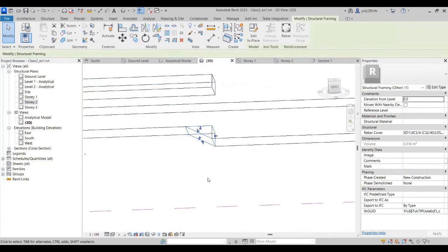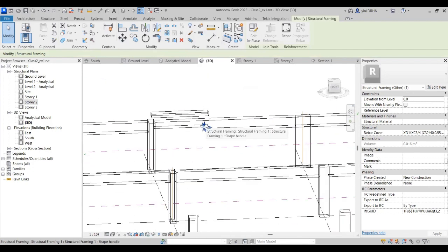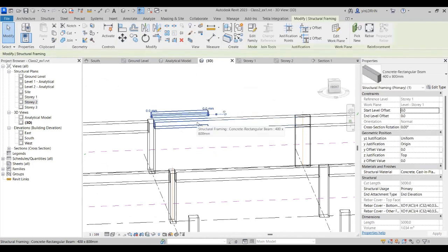So we have this, our haunching. Haunching we can do this way. And similarly, if you want to lower down the slab, you can do the same way. Lower down the particular level, then you can draw your haunching. So these all are the modeling, and it may affect your structural analysis. So even though we have the haunching, we can keep our analysis line at the center, then it may not give issues.